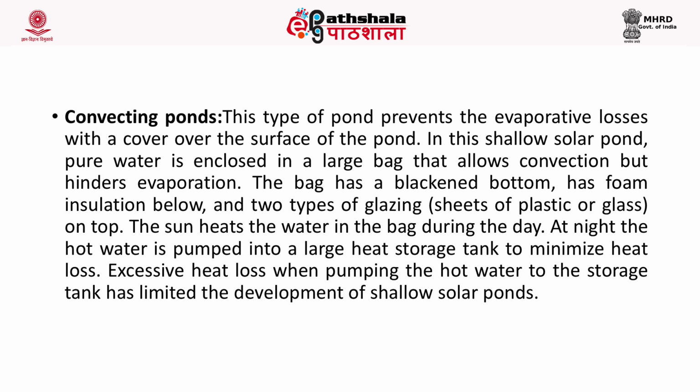The bag has a blackened bottom, it has foam insulation below and two types of glazing, sheets of plastic or glass, on the top. The sun heats the water in the bag during the day. At night, the hot water is pumped into a large heat storage tank to minimize the heat loss. Excessive heat loss when pumping the hot water to the storage tank has limited the development of shallow solar ponds. So most commonly used ponds are of the non-convecting type,